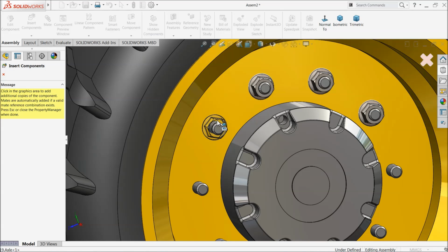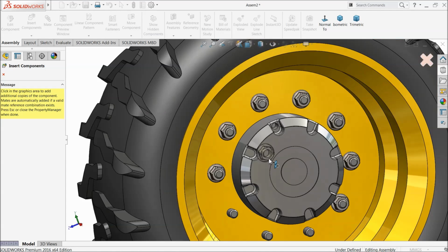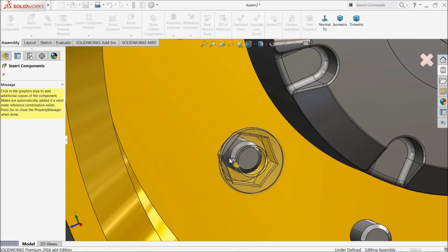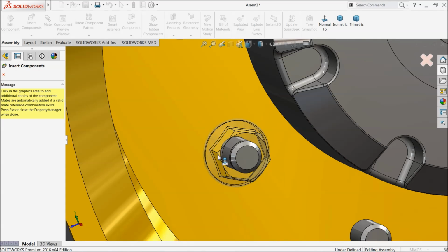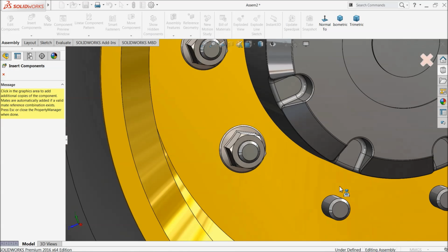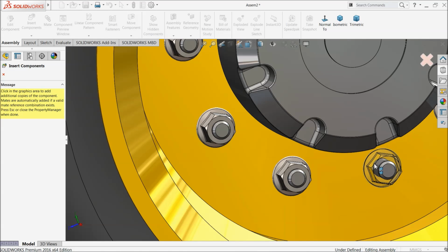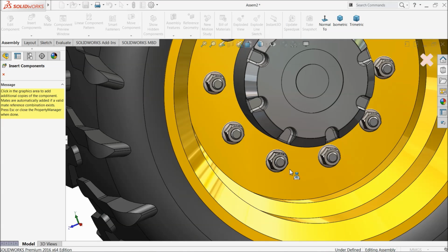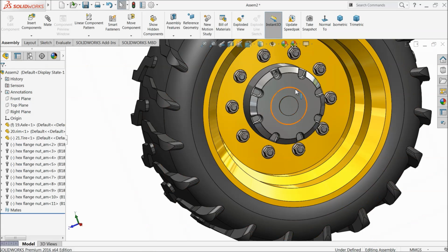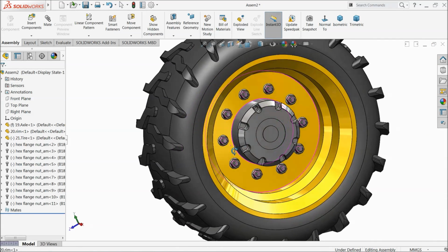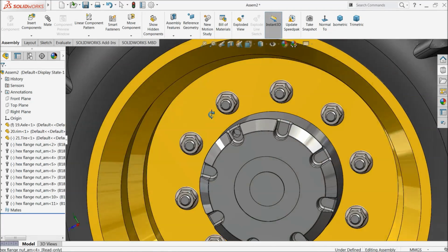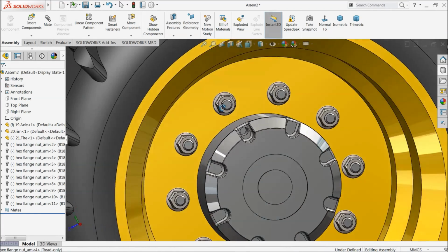Surface, surface, surface. Just first go to this round rod, then go to the surface, and it will automatically take the position. This is a simple and easiest way to fix the nut. Select cancel. Now see here, we fixed all the nuts and we selected flange nuts, so there is no need for a washer.